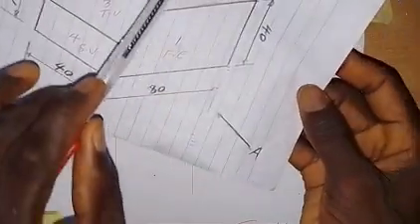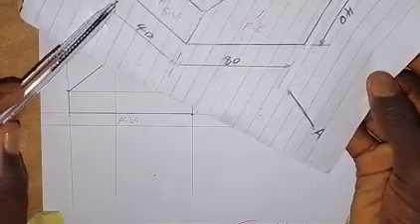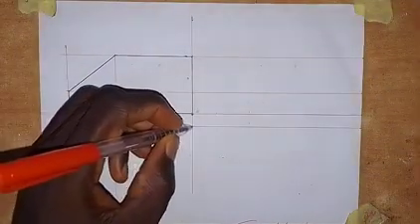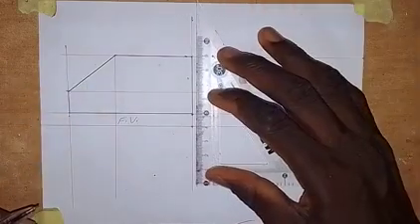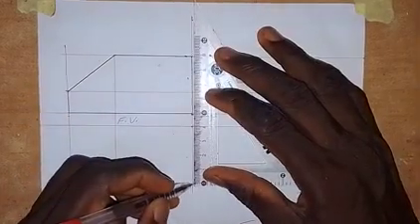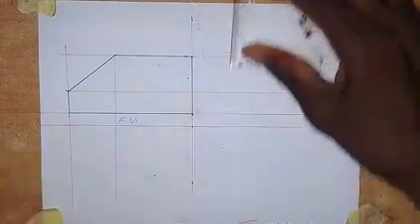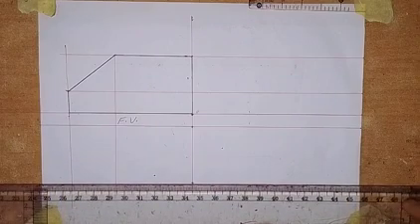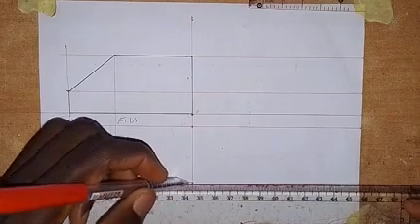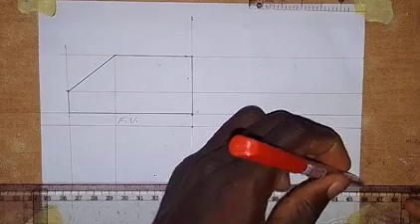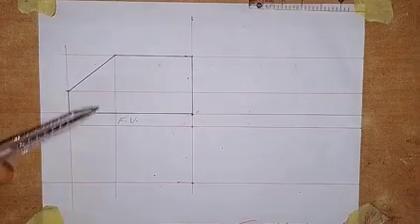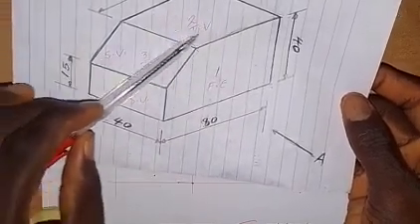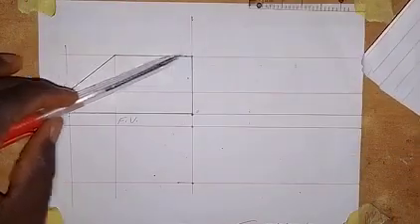What we just need to do is take the width from here to here. The width is given from here to here as 40. So we have to take 40 millimeters from this point down. So this is 40 millimeters. And as I said, any measurement that you take on the vertical, you have to draw a horizontal line. So here we draw a horizontal line to this side and we also draw to this side. If you look at what we have here, this surface, this face that we have here, which is shape 2, is along from here to here.